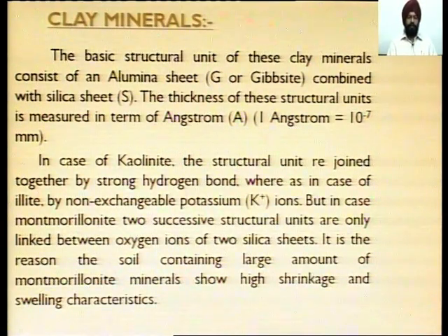But in case of montmorillonite, two successive structural units are only linked between oxygen ions of two silica sheets. It is the reason the soil containing large amount of montmorillonite minerals shows high shrinkage and swelling characteristics.